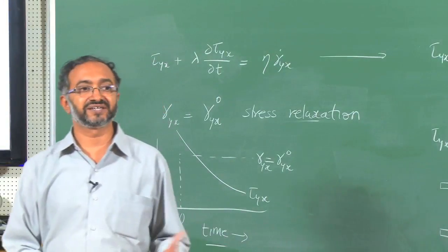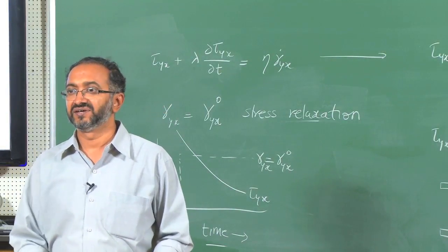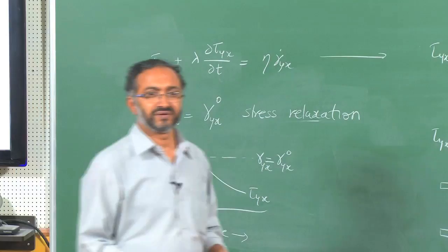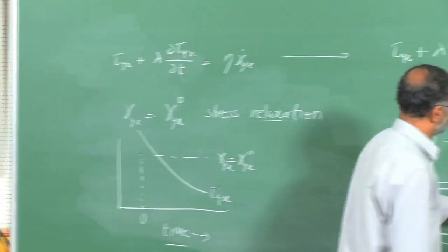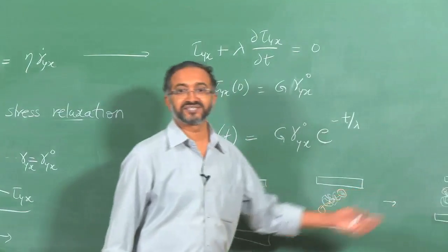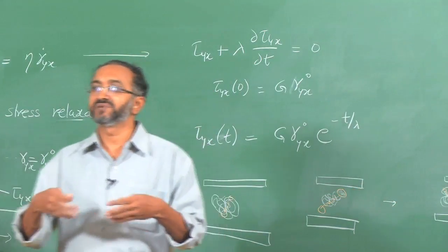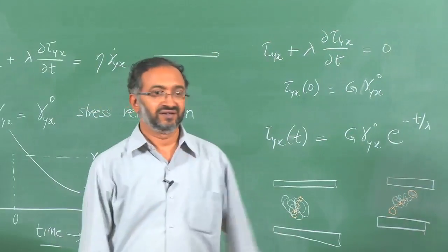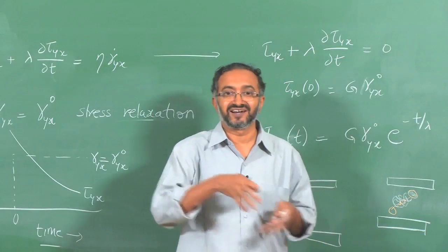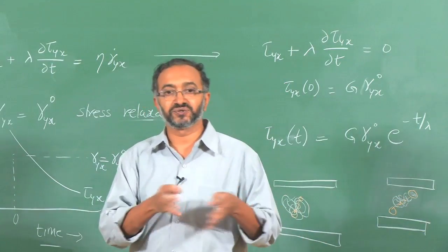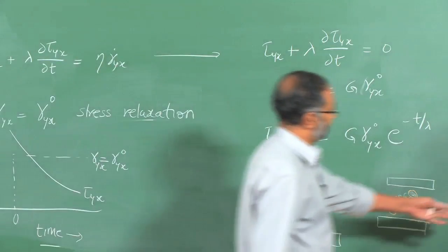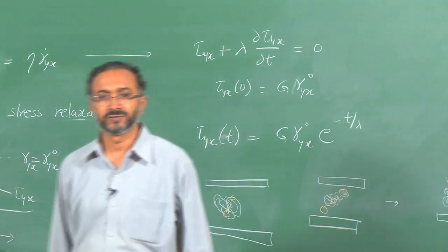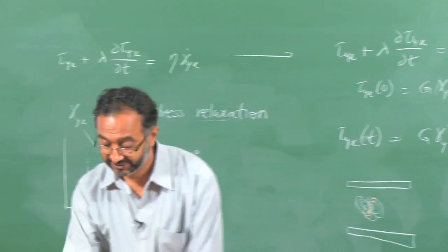So, that is why the macromolecule is able to relax through segmental relaxation and other modes which are present. The macromolecule is undergoing mechanical relaxation because its segments can move, there is bond rotation around the macromolecular chain, and because of these things this molecule which got stretched at 0 time is able to come back to equilibrium state. So, now a new equilibrium stress-free state is again obtained. Do we call it equilibrium state or steady state? In this case it is an equilibrium state, right.